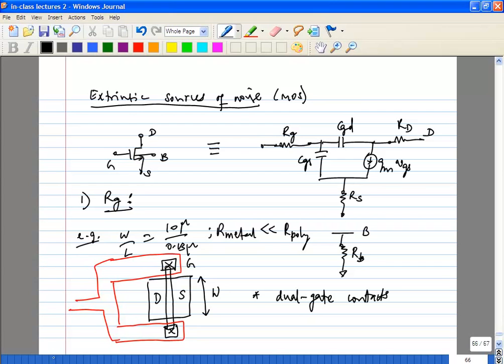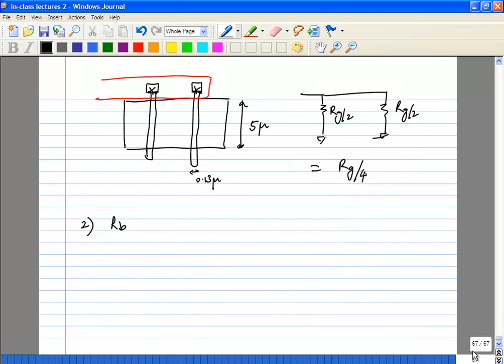Your bulk will have a common connection for the overall chip, but that will be very far away from your transistor, from the bottom side, at a 500 micron depth. So you'll have to make sure this transistor has a good bulk contact. To do that, if you look at normal RF layouts, you'll see something like this.